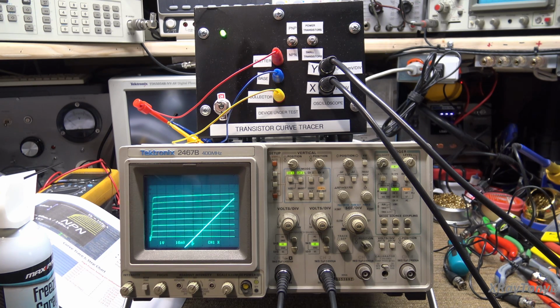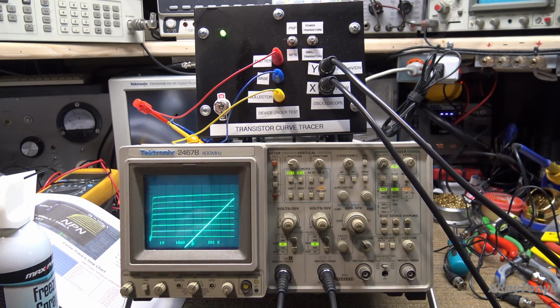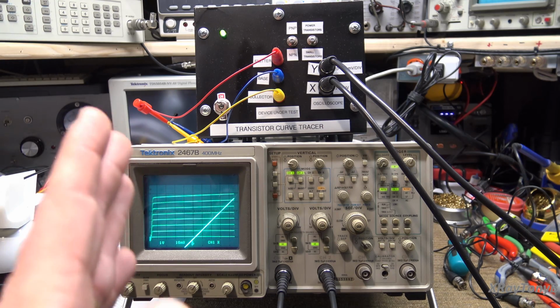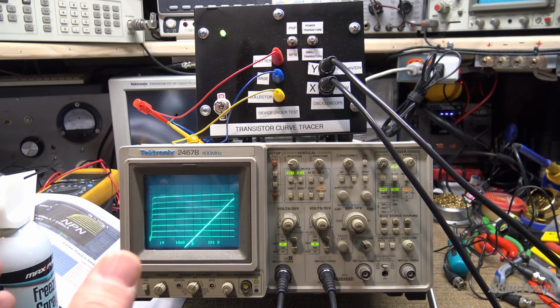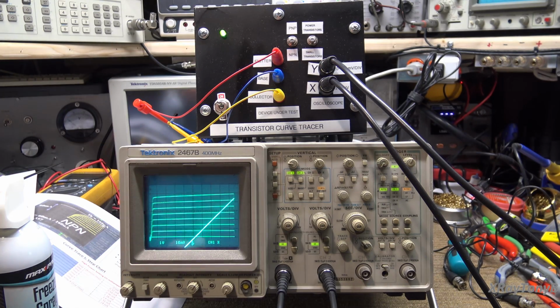And once you reach a certain point where the frequency of the signal is faster than the amount of time it takes to turn the transistor on and off, the transistor will no longer have any gain. Okay? And we call that point where the transistor becomes unity gain its transition frequency. So the closer we get to that transition frequency, the lower the forward gain is going to be of the transistor.